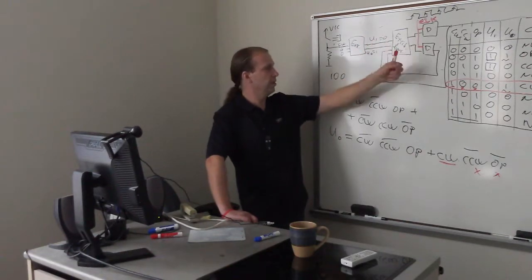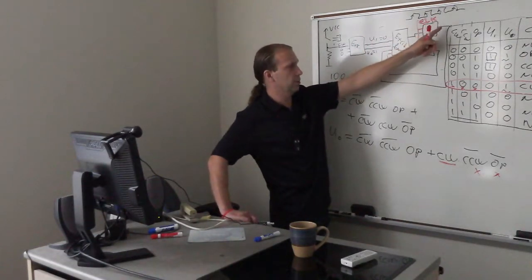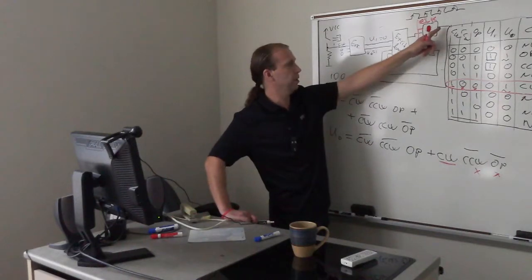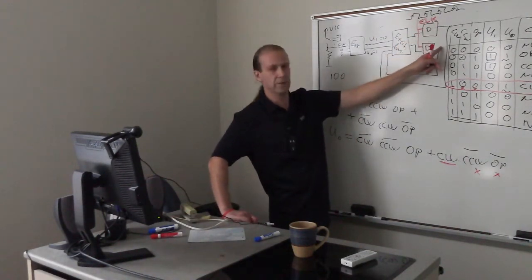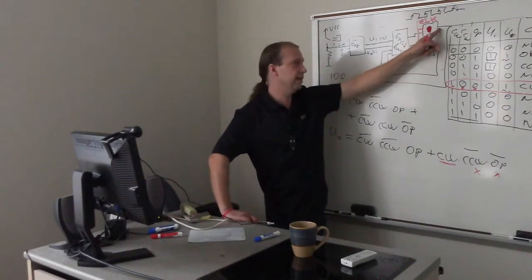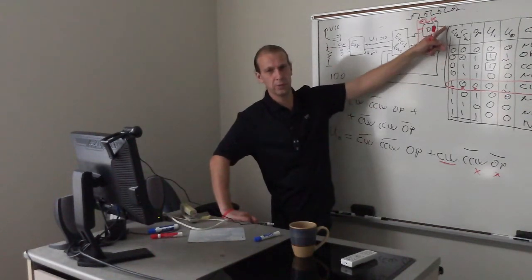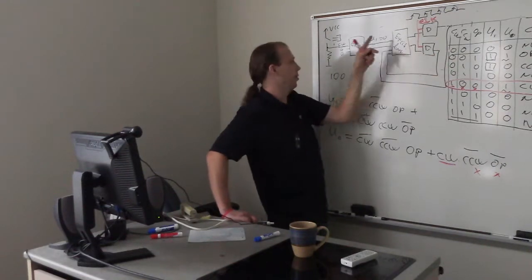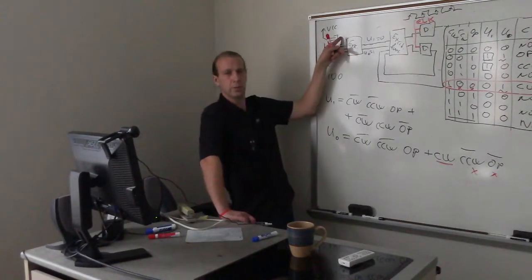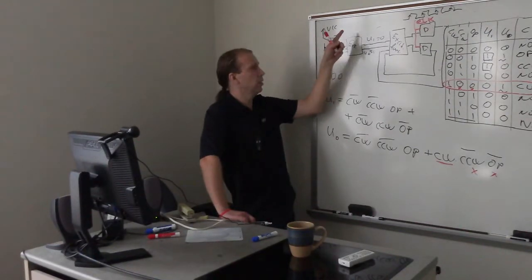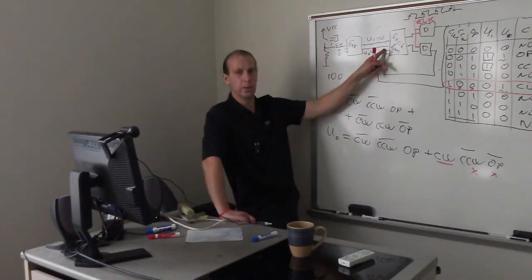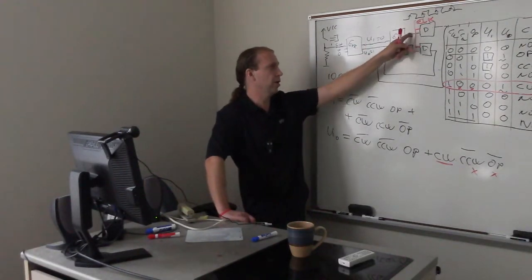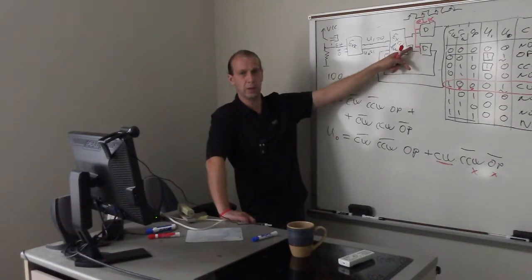But the point is, the 2 bits which we memorize in the trigger represent the state of the finite state machine. And that state will continue to change for as long as we press and hold the push button. We pressed it, we hold it, and the combination here is 0, 1. That combination will result in a certain command here.